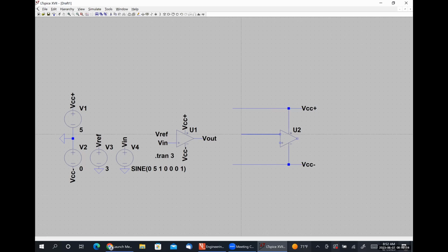I apply my reference voltage to the inverting input node. So I'm going to move that stub of wire out there, and I'll set up those resistors in a moment. My input is applied here. So let's do VN. I'm going to call this output node Vout 2, and I need to do that because the system will get confused if I have two nodes labeled as Vout, because that's where we're measuring at.